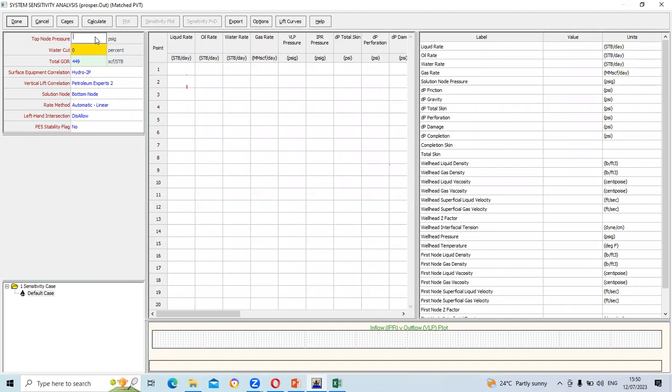So from here now, we need to know the pressure at the wellheads. Remember that the bottom hole pressure has to always be greater than the wellhead pressure. That's the reason why fluid is flowing from the bottom hole towards the top of the well, right to the surface. So if your wellhead pressure is greater than the bottom hole pressure, there is no way fluid will ever flow. So at this level, we will just leave it simple at 200. Our water current, we started by saying it is 0. So let's leave it at 0 first for now.